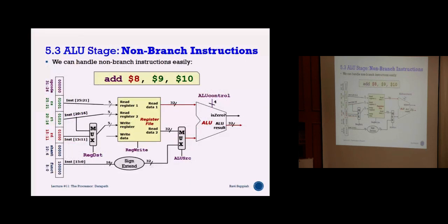Okay, now let's look at this addition of the ALU block. So far we saw until here. Now we are adding the ALU control block. So what is the difference? Actually nothing much, because we know that in the first stage, which is the decode stage, you already have two 32-bit numbers ready for the ALU operation.